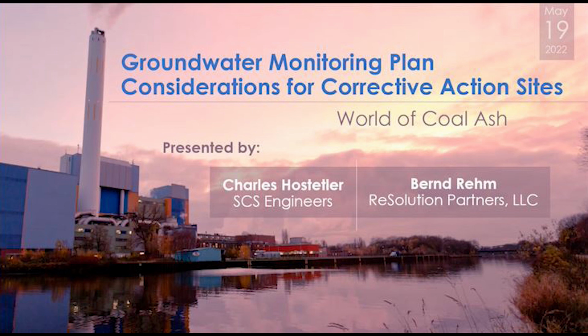That's correct. I mean, there's what's required in the regs, which we're not saying you don't follow the regs, but in addition to that, if you want to understand what's going on, there are some other steps you might want to take. Because it can really confound things if there's a lot of suspended sediment. It doesn't even take a lot of suspended sediment. Even if your NTUs are in a few tens, you might have enough suspended sediment there that when you're measuring these trace metals at the microgram per liter level, it becomes important.